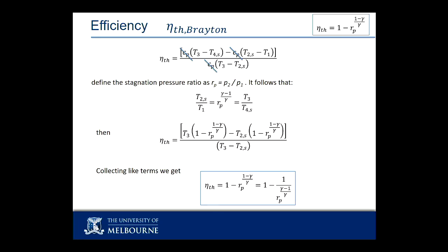What that last expression means is that my efficiency for a gas turbine engine is absolutely defined the moment that I choose a working fluid, air, and the moment that I choose a pressure ratio. So if I want my efficiency to go up, I need to increase my pressure of the compressor. I need a bigger compressor. So I get the world's biggest compressor and I put pressure up to infinity.